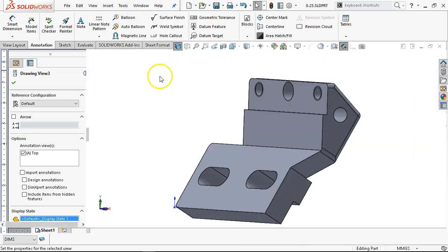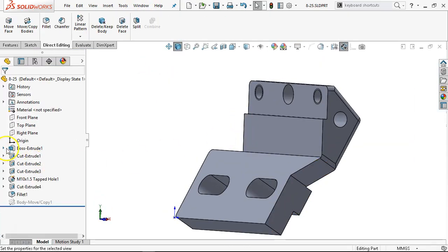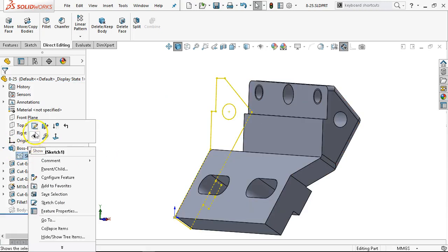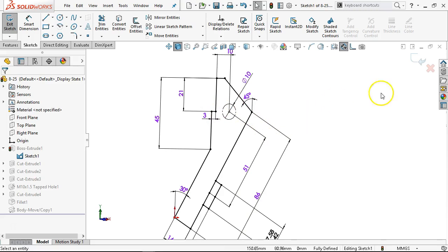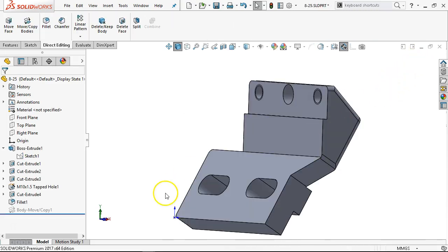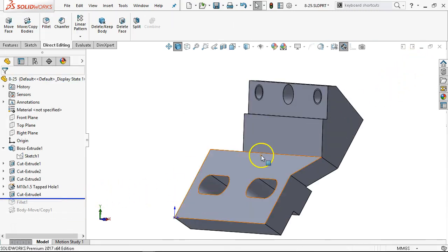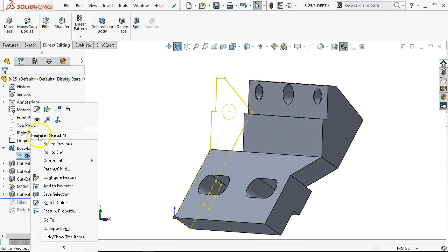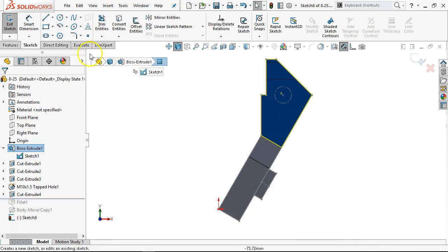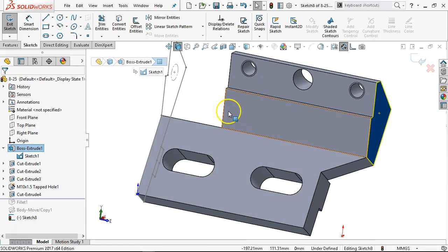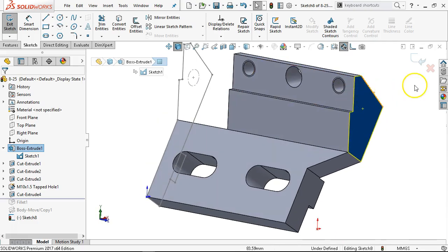We'll jump back into the part. The very first sketch, we're going to switch that circle over to construction geometry. All right, I want the fillet to be the last feature, and I'm going to go ahead and pick up the hole geometry on the end face. Let's see, it doesn't say anything, just 10 millimeters to a depth of 19.